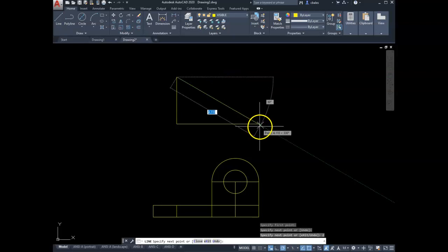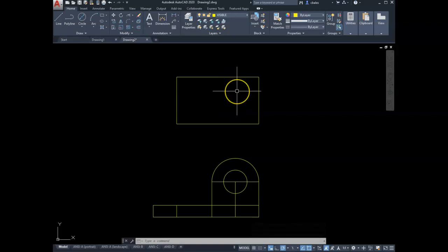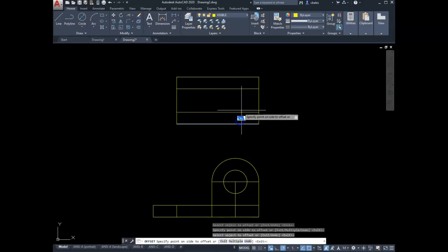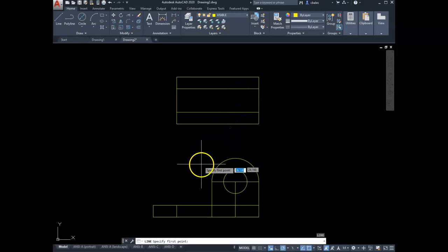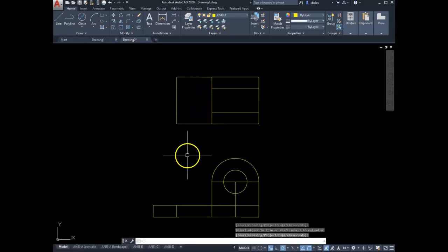It's a radius of 1, so it's a total width of 2. And then we can track that, and we can close that. So we got our partial top view. The thickness for the vertical centers up here are 0.5, so I can offset 0.5 like this, and I'll draw a line from here up to here. And then I can trim this off.